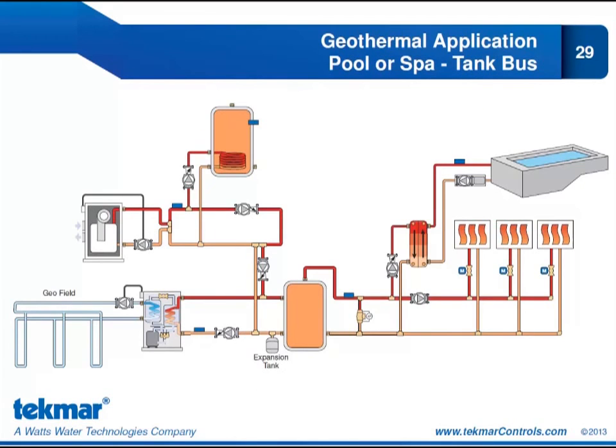Now, if I did want to take advantage of geothermal heat and include the pool or spa in my tank bus, I can do that as well. Here's an application showing that very principle. So here off my tank loop, I'm going to have my heat exchanger for the pool or spa and my 3 radiant zones.